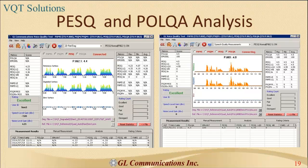Now, unfortunately, you can't run PESQ and POLQA together at the same time on the same file, because there are differences in the files that the two algorithms use. POLQA requires a very specific file that the ITU provides, male and female, whereas PESQ uses pretty much any file except those files. They're not really formatted properly.